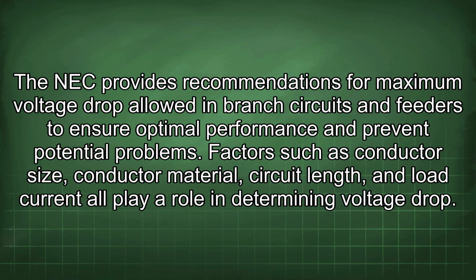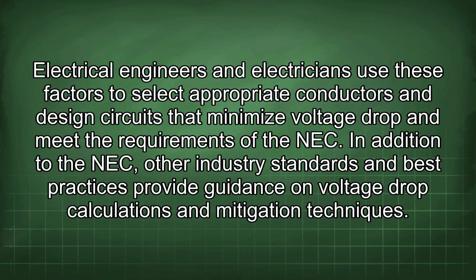Factors such as conductor size, conductor material, circuit length, and load current all play a role in determining voltage drop. Electrical engineers and electricians use these factors to select appropriate conductors and design circuits that minimize voltage drop and meet the requirements of the NEC. In addition to the NEC, other industry standards and best practices provide guidance on voltage drop calculations and mitigation techniques.